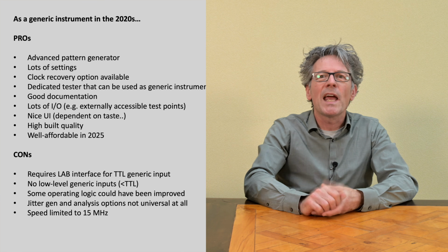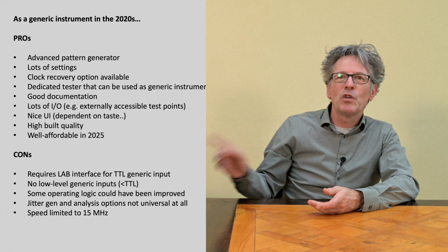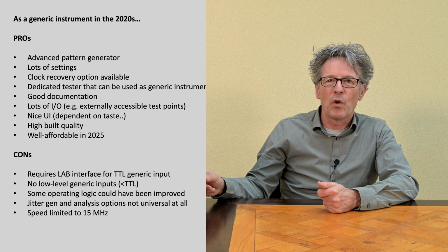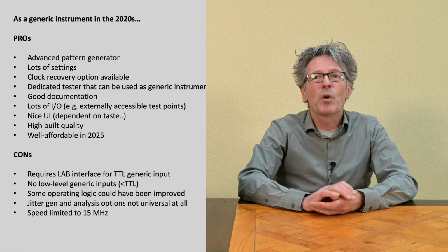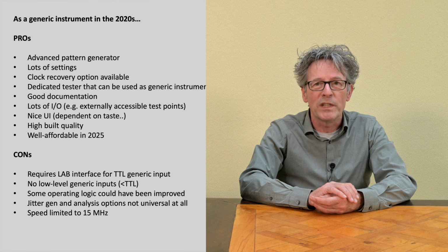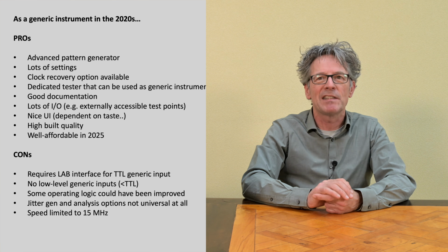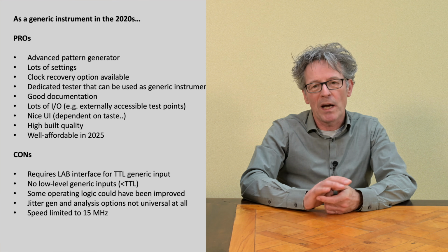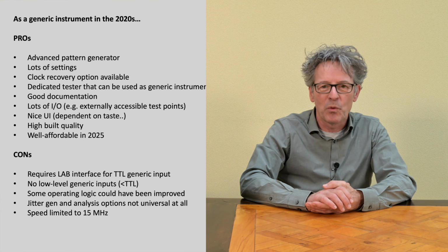But should you not be able to find one, I think that if you take the serial port RS232 input on the back and the machine is just running in synchronous mode, it probably just takes a level converter, so a chip like the MAX232 or so, that would do the same trick, and I think that would create exactly that TTL input for you, although I haven't tried it because I already got the LAB interface, but I think that will be your way out basically.